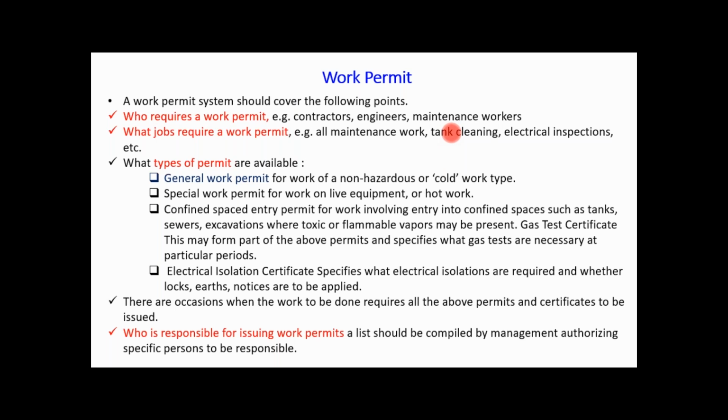If the hydrocarbon gases are there, that may be oil, that may be gases like LPG, hydrogen, etc., then these gases are flammable or explosive in nature, and in case of any cutting, grinding, or welding operations, an explosion may happen. So all these things should be kept in mind, and we have to check them with a proper tool and with a proper process only.